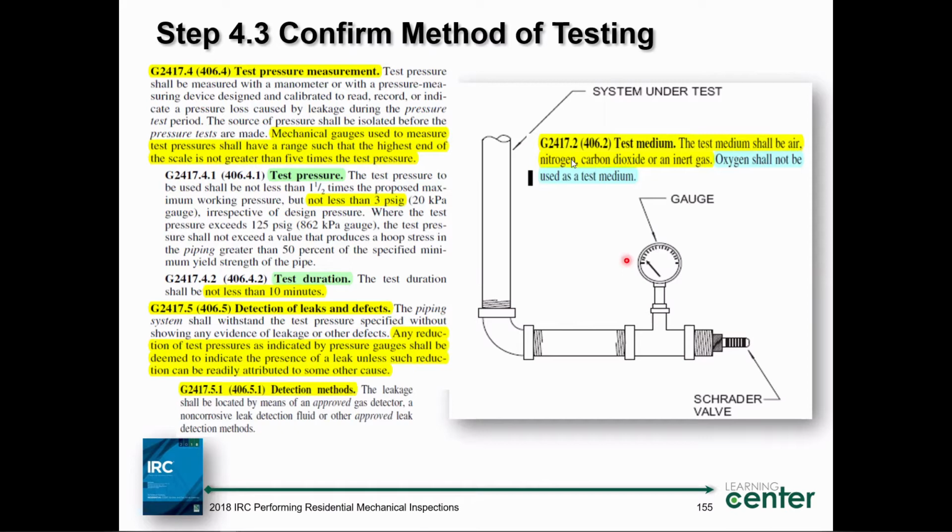What you're ultimately trying to do is wipe all the joints, or take your combustible gas detection sniffer, locate each joint, and verify that there are no small leaks coming out of the joints. So yes, you are to do the leak detection as well as the pressure test. It's two parts, not just one part. Does that help?